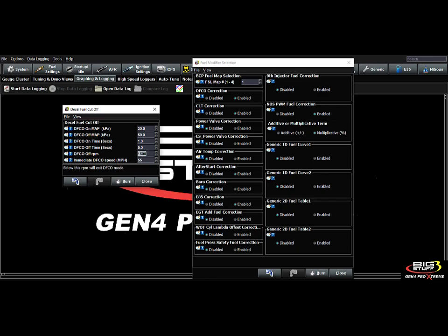If we get below 1500 RPM, no matter what, we're actually going to bring the fuel on. And if we're above 55 miles an hour, there is no time delay at all. So all this is configurable. This simply will cut the fuel off completely. You'll hear the tone of your engine change. It will bring no fuel on your motor.